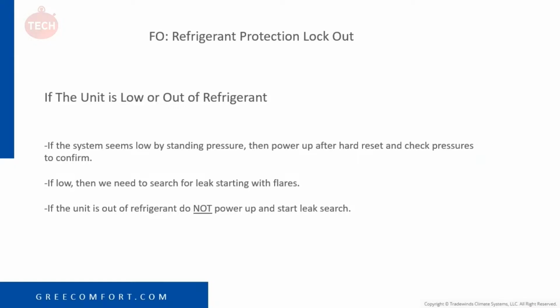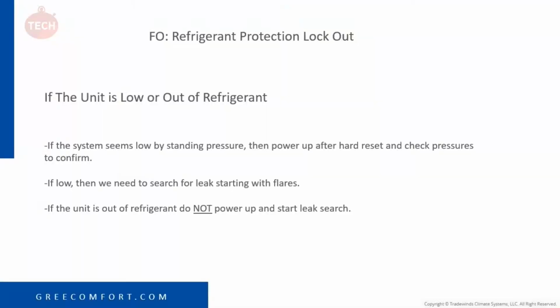If the unit is low, then we need to search for a leak. Ideally, you want to start with the flares. That's where most of the leaks are. If the unit is out of refrigerant, do not power the unit up. And then we need to do a leak search. Again, we want to start with checking flares.